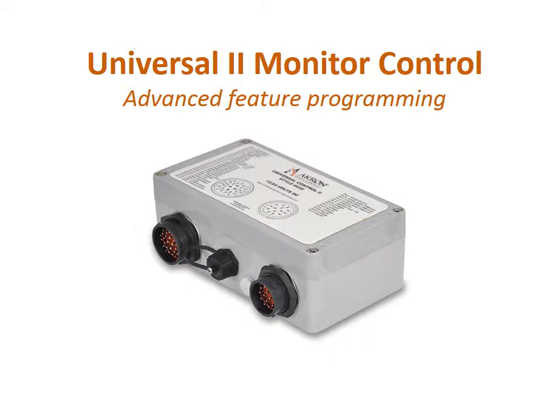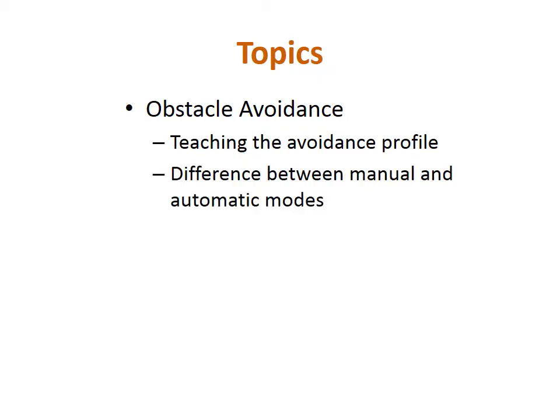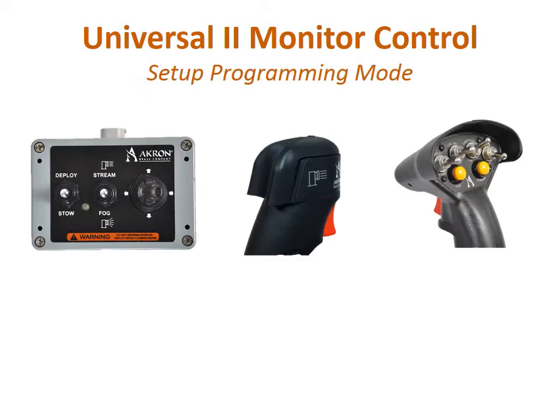Today we will be discussing the Universal 2 Advanced Monitor Control System Setup Programming Options. During this educational video, we will learn how to set up the obstacle avoidance feature. We will learn how to teach the avoidance profile and discuss the difference between manual and automatic avoidance modes.